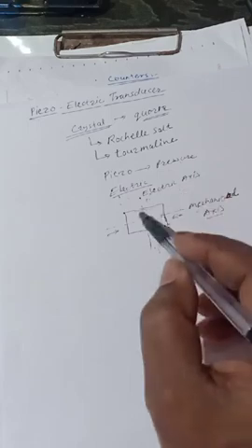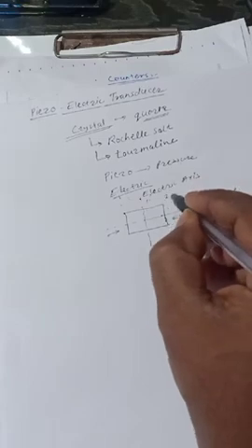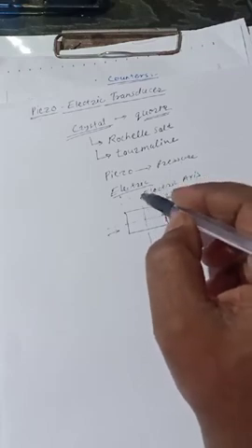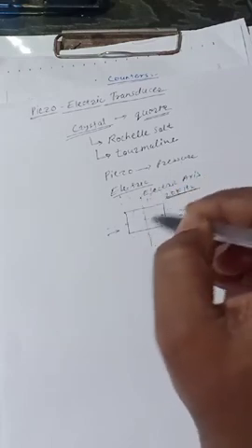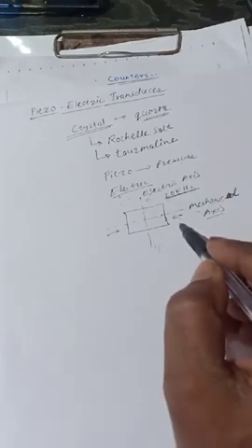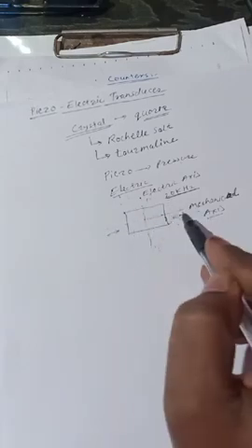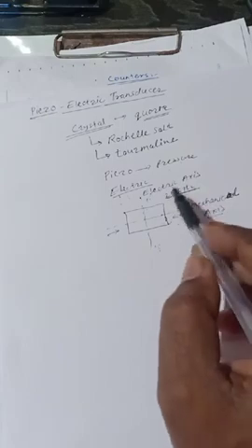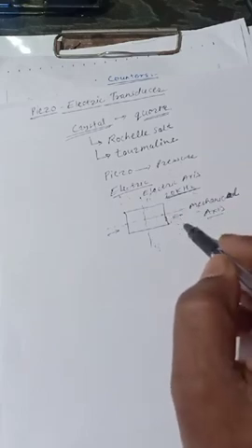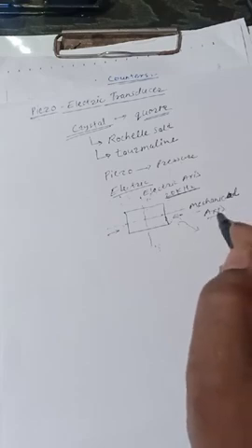And vice versa, if I apply a variable electric signal, say beyond 20 kilohertz, an AC signal on the plates of these two sides, then it generates mechanical vibrations on the mechanical axis. These vibrations are nothing but ultrasonic waves.